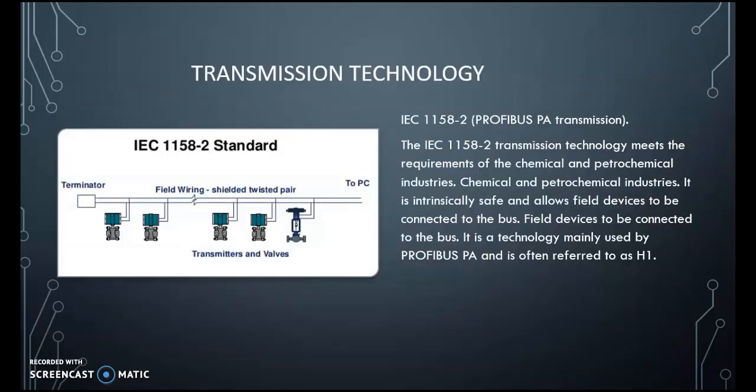And finally, the transmission technology. The IEC 61158-2 transmission technology meets the requirements of the chemical and petrochemical industry. It is intrinsically safe and allows field devices to be connected to the bus. This is a technology mainly used by Profibus PA and is often referred to as H1.